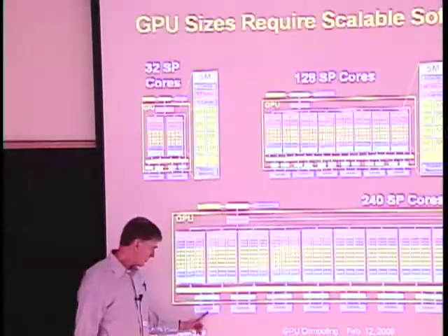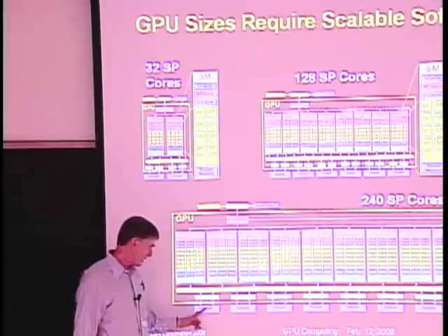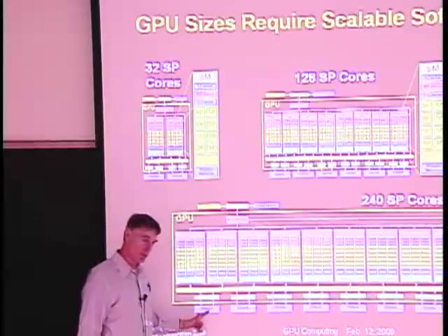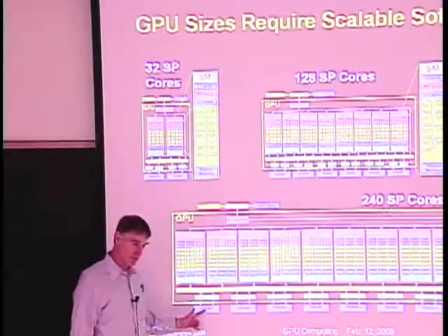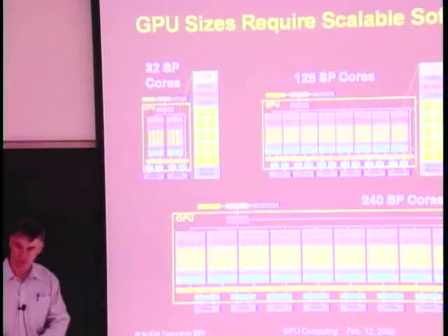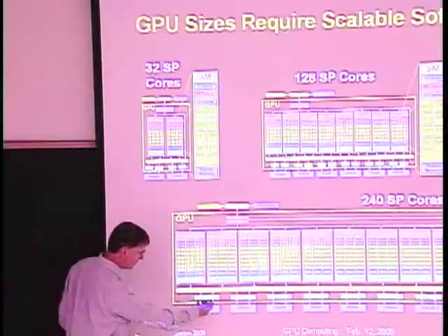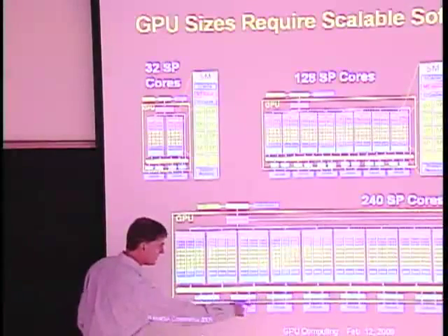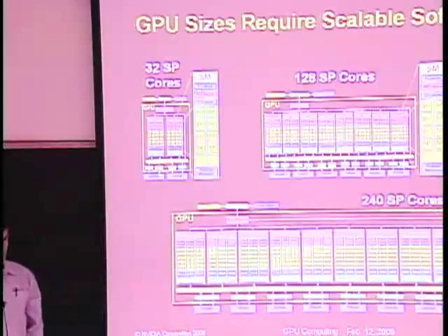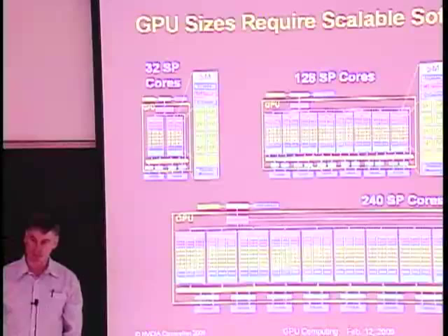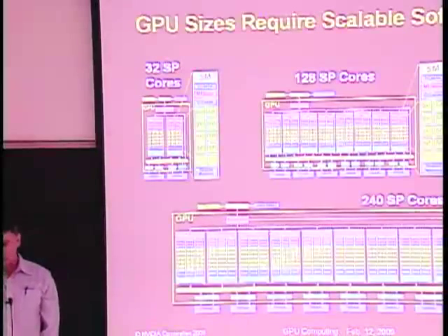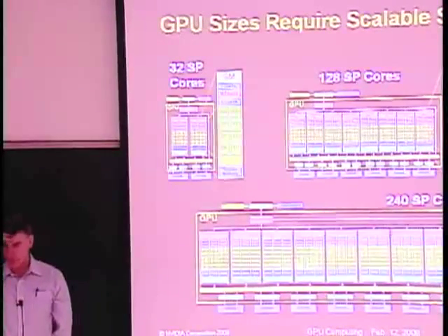So this physical DRAM is probably 2 or 4 physical DRAM parts. Okay, it's hard to get a DRAM part with more than 32 data bits of pins. So there's a lot of bandwidth here. The aggregate bandwidth on a GTX 280 is, I forget, 150 gigabytes per second, something like that. CPUs just don't go that fast.